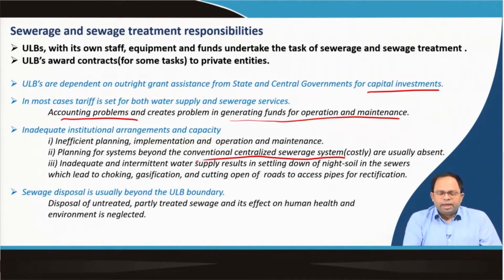And then inadequate and intermittent water supply results in settling down of night soil in sewers. So, this is another big issue. That means, because we don't have 24-hour water supply systems in Indian cities, most of the situation is where we have maybe a couple of hours of water supply in the morning and in the evening, and during the rest of the time there is no water supply. So, that actually leads to settling down of night soil in sewers.